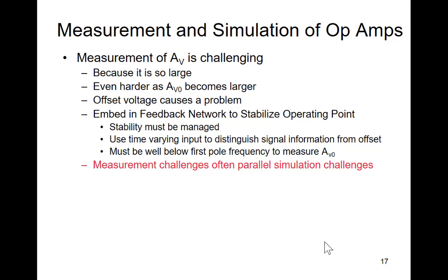So what do we do when we get in trouble with this gain not being high enough? If you want to build an amplifier with a gain of 100, and your op amp gain is only 100, your circuit's not going to work very well at all with feedback. So what we do if we want to build an amplifier with a gain of 100, we might build 2 amplifiers with a gain of 10.